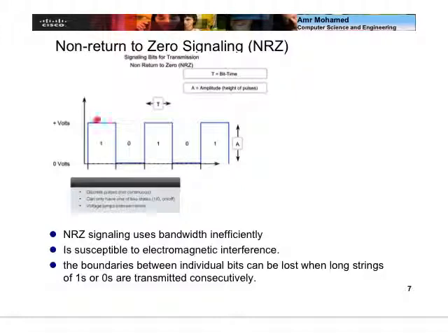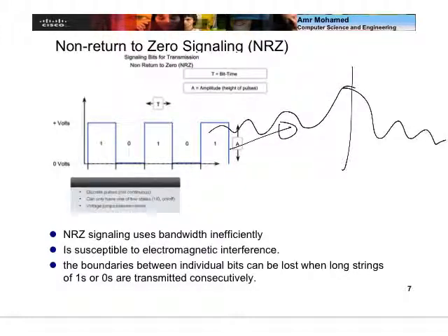this square kind of signal gets converted in the frequency domain into something like this. Whenever you have a continuous signal with sharp downturns like this, it actually turns out to have high frequency components at multiple frequencies in the frequency domain.